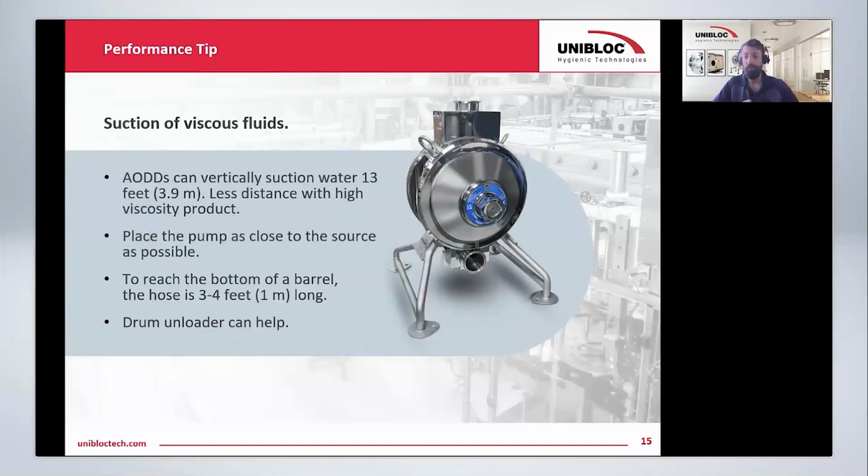And so for a conventional AODD, it's going to be 4 inches or so because they've got that inlet manifold. And for the alternative style AODDs, it could be around an inch because the inlet is right at the product chambers. You don't have that manifold pipe work.